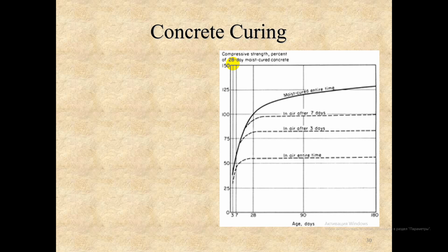Achieving its design strength depends to a large extent on the care the concrete is given in the first few days of its life. In particular, the concrete needs to be cured when young. This is an important aspect of concrete management and requires further explanation.